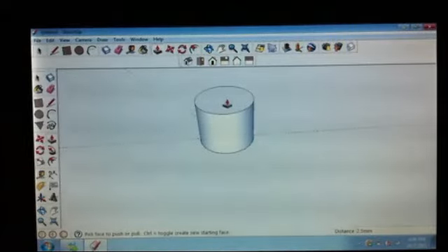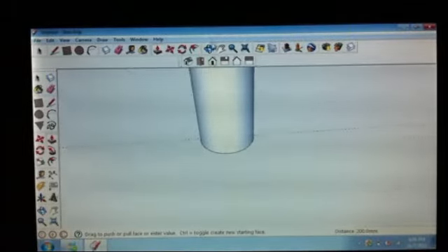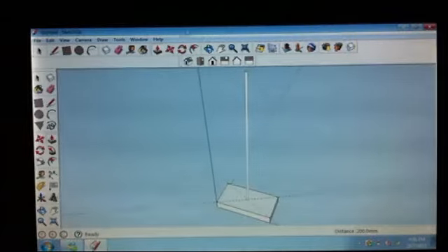In this case, you can see here is 2.5 mm. The rod that you have is about a ruler length that could go up to, let's say, 200 mm, 20 cm. So I key in 200 and enter. Same thing, you zoom extend, you can see that the rod is out already, because the whole picture is here. Now with this part done, you can see that the rod came out from the surface of this base. So it actually didn't punch through.